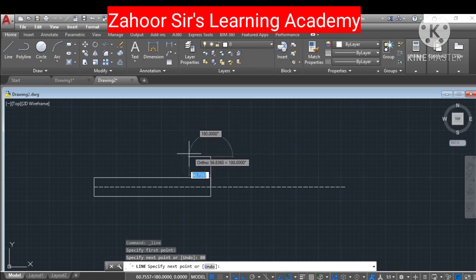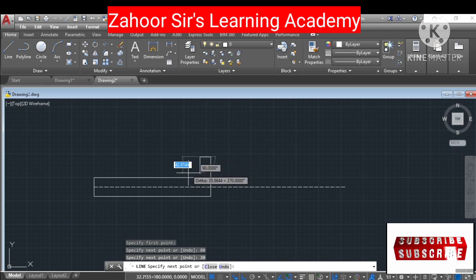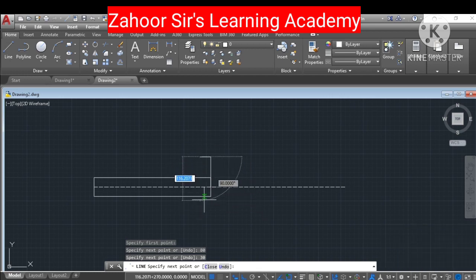Then I go to the left side 30 mm, write 30 mm, then press enter. Then I have to go downwards from this point to this point. As I said, this is 160 total, so I'll go downwards 160, then press enter. Then to this end I'll go 30, enter, and then connect this point with this, then escape.